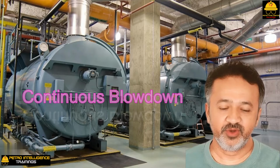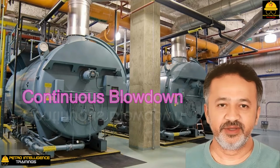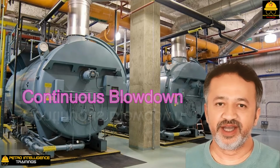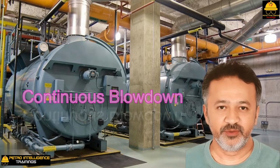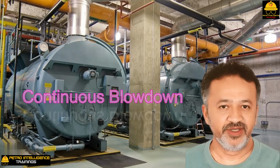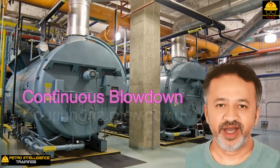If steam is used to drive turbines or will be superheated, then the TDS content of the steam is quite important. A good target for silica is 0.02 mg per liter silica in steam used for turbines or for a boiler operating from 300 psig to 600 psig. 0.4 total caustic alkalinity as milligram per liter of silicon dioxide in BFW.